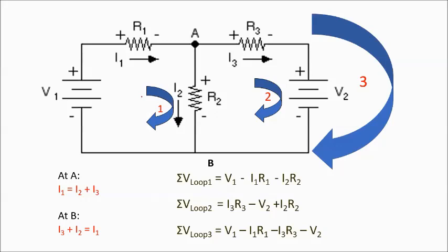No? Okay. So, let us analyze. At point A, ito yung point A. Summation I, this is summation I equal to 0. Ang ibig sabihin nito, I entering is equal to I leaving. So, at point A, what are I entering? Isa lang. Si I1 lang entering, leaving I3 and I2. So, ma-present natin yan as in this presentation. So, I1 is entering equal sa I2 and I3 leaving.